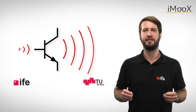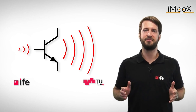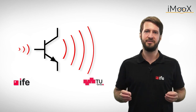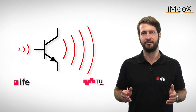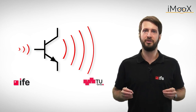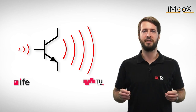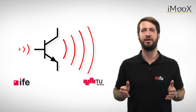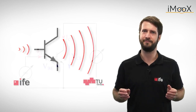We also find that the amplifier has a nonlinear behavior if the emitter resistance becomes zero, which means that the output signal will not look at all like the input signal. We would also notice that the biasing changes with temperature. So clearly there's something wrong with our simple transistor model. Maybe it needs some modification.